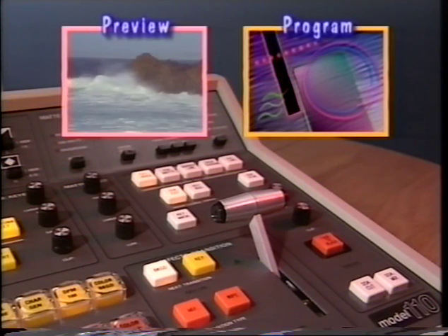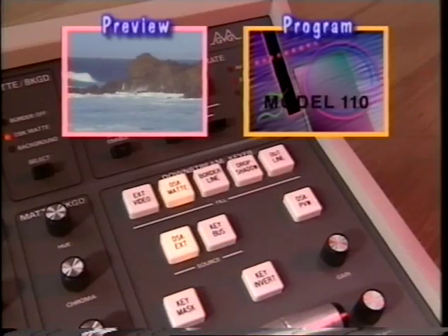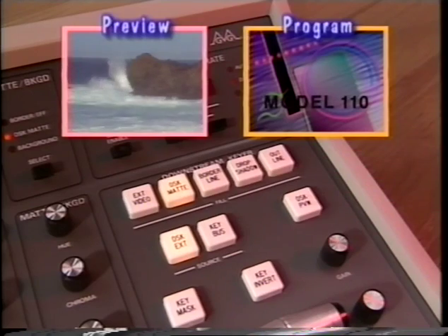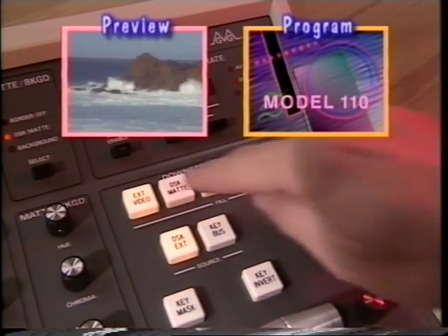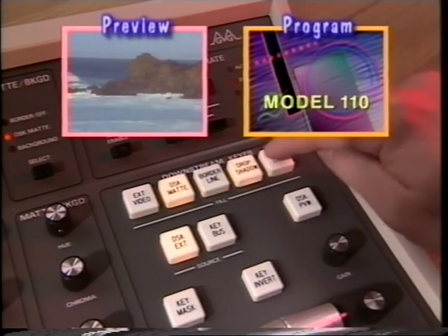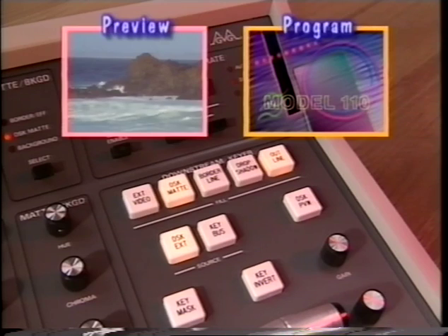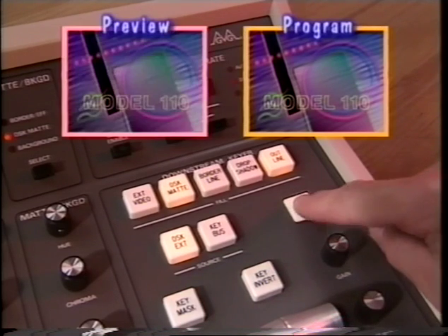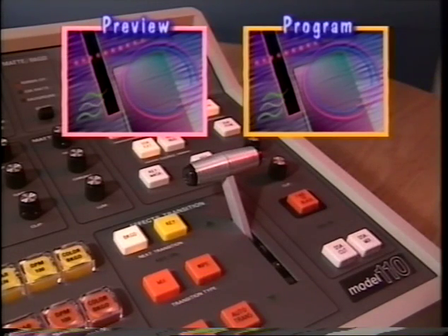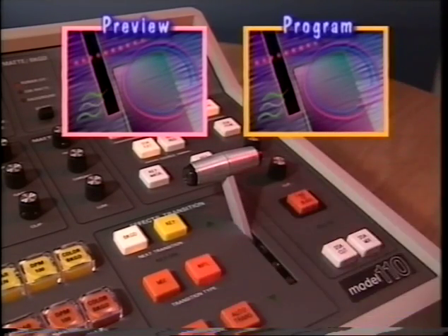The downstream keyer group, or DSK, is where you can select and control downstream key effects. Source push buttons select video signals used to cut the keyhole. Fill push buttons select the video signal used to fill the keyhole. Borderline, drop shadow, and outline produce a border, shadow, or matte-filled outline around the key if the borderline option is installed. Downstream key preview causes the key to appear on the preview monitor. It turns off when the key is cut or mixed on air, when the output is faded to black, or when effects transition push buttons are pressed.